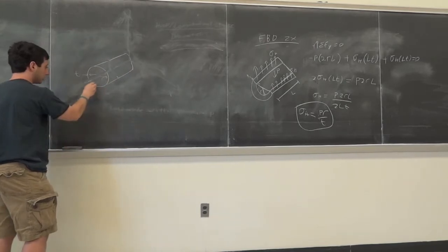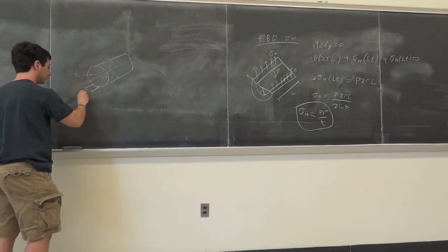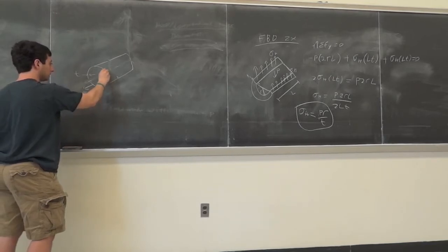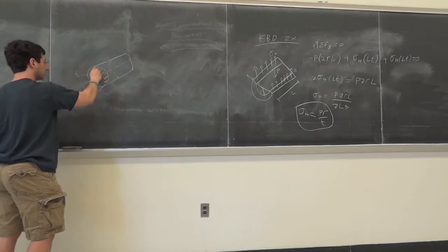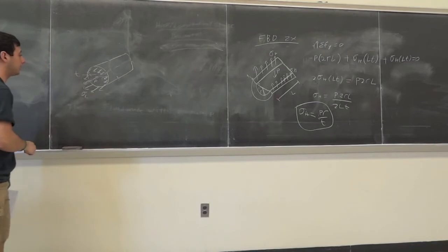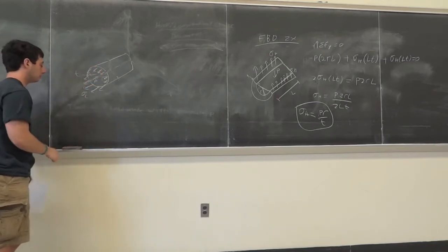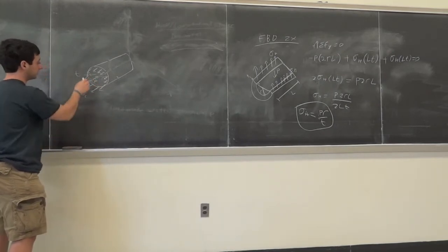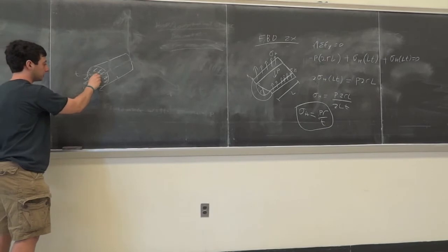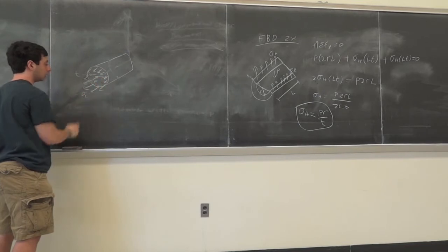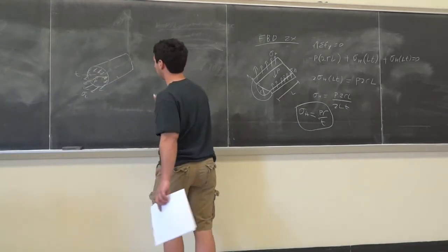Okay, so there's stress all along this area. This is sigma L. So it's acting along this face. Right? And then there's a pressure in the center. So this is P. Okay? And P is acting all along this area. Okay? So, can you guys see this? The wall thickness is T, and from the center of the circle to the inner wall is R. Okay? So we have to do another force balance.